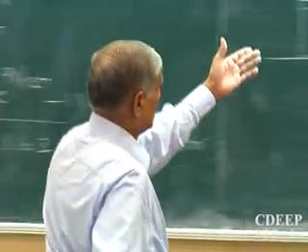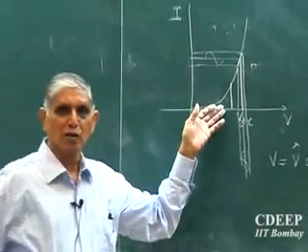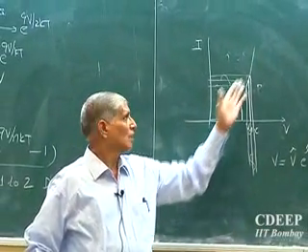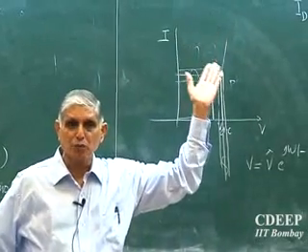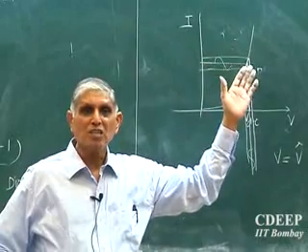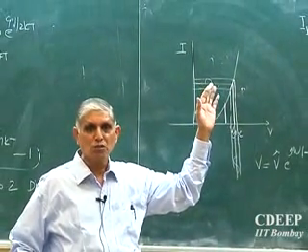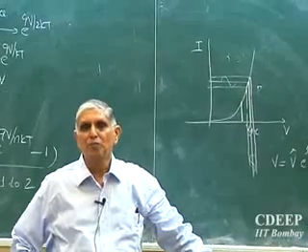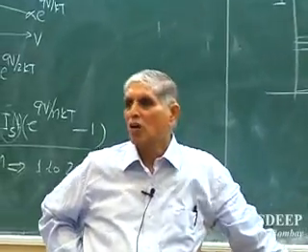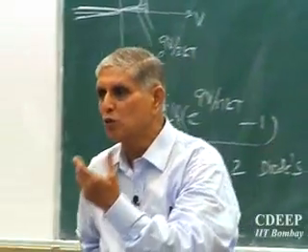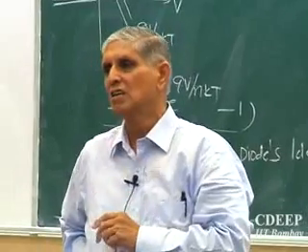Is that clear to you? This is very relevant, which is why people are worried about where you bias, because I have just shown you, if I put I_DC, V_DC somewhere else, R will be different. If I do it here, it will be different, because it is not linear, it's an exponential function. So obviously at whatever V_DC or I_DC you use, the R will be different. So one must know what your biasing point is. That is why we say in circuits, when the device is put, how do you bias it? That will decide the performance.